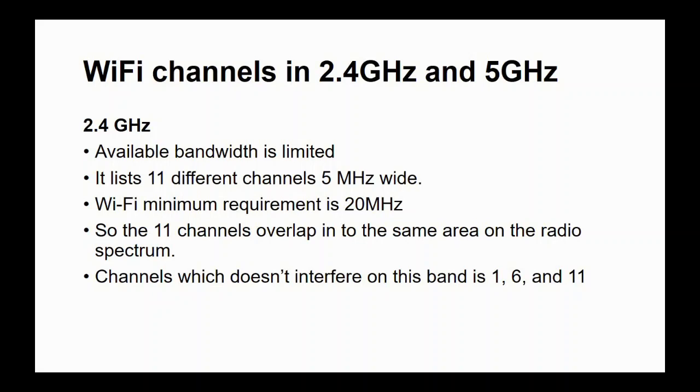Not all the channels are allowed in all countries. 11 are allowed by the FCC and used in what is often termed the North American domain, and 13 are allowed in Europe, where channels have been defined by ETSI. The Wi-Fi channels are spaced 5 MHz apart, with the exception of the 12 MHz spacing between the last two channels.